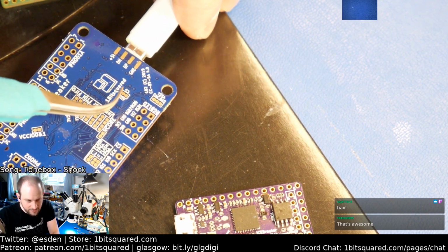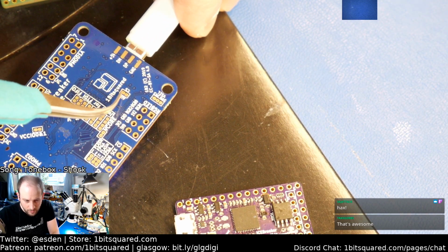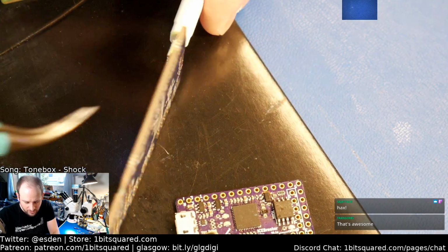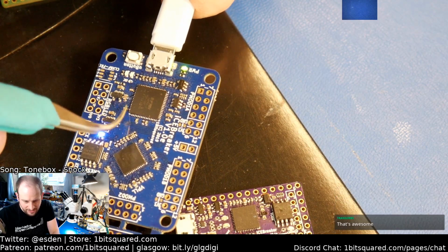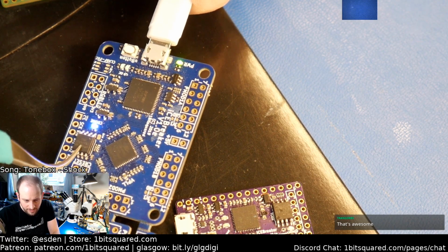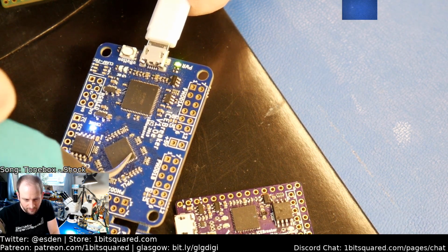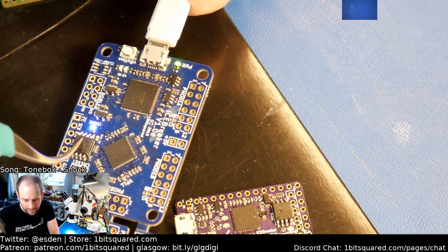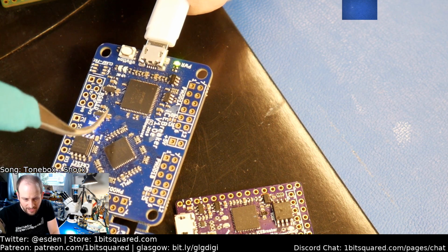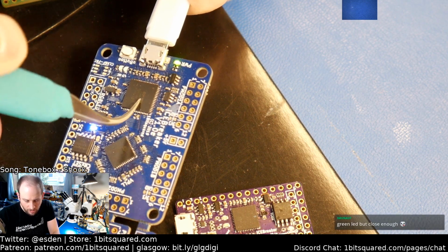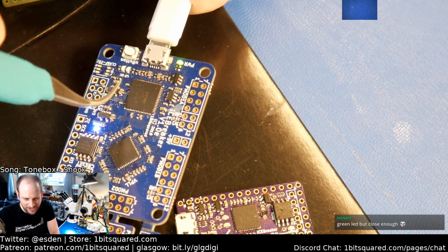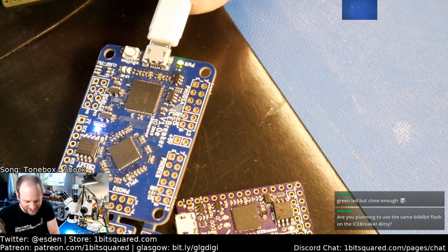So this aux chip select, which is normally closed, is an additional line from the FTDI chip connected to the red LED signal, so that after the flash chip is flashed, and the FPGA loads its bitstream from the flash, you can use the SPI interface and the additional aux chip select to talk from the FTDI chip. Green LED? I think it was the red LED. The green LED is the SPI one. Anyways, details.